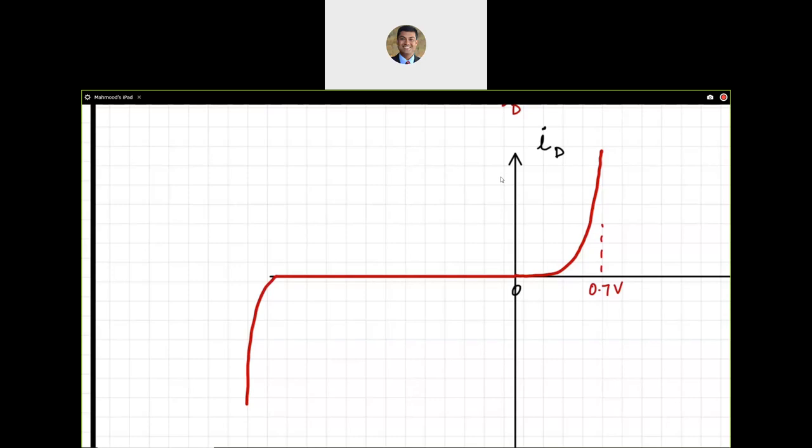So around, say, negative, maybe a few hundreds, negative 100 volts or beyond, that's when it is going to break down. That means it cannot hold that depletion layer any longer. All that current, all that charge is going to flow through that diode, and it's going to go in the reverse bias region. So the current is going to be negative. But that happens at a very, very negative 100. So it's way down in the negative power supply.